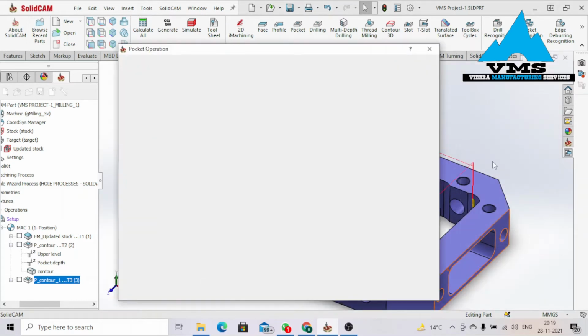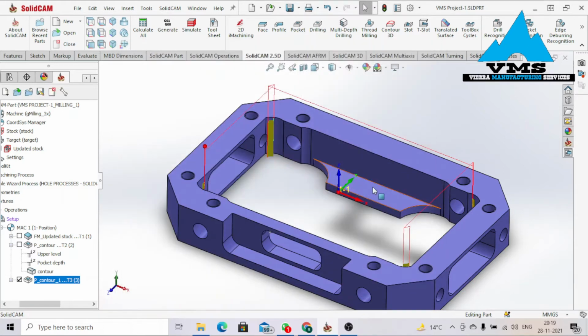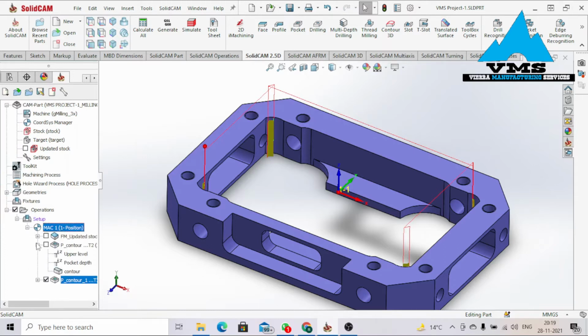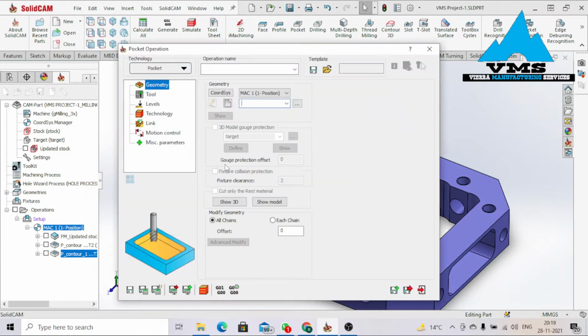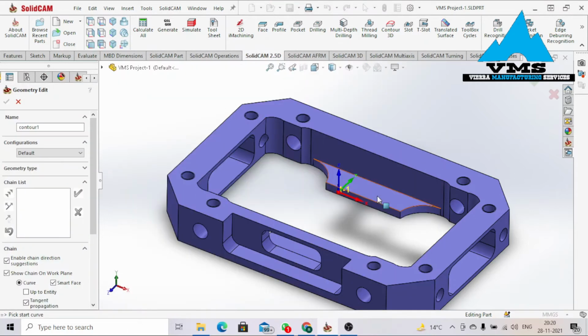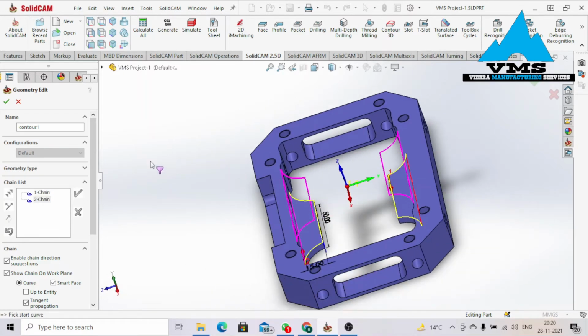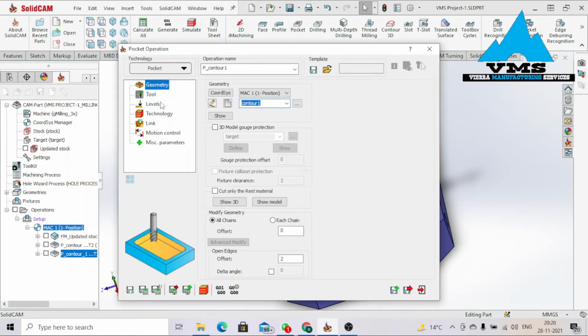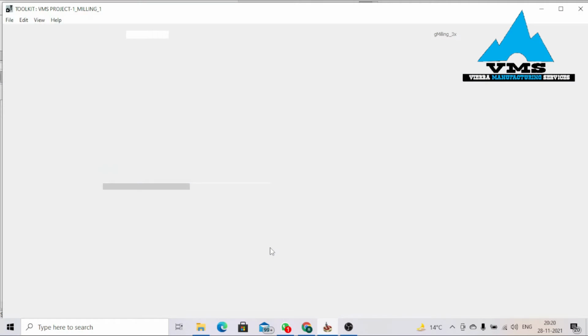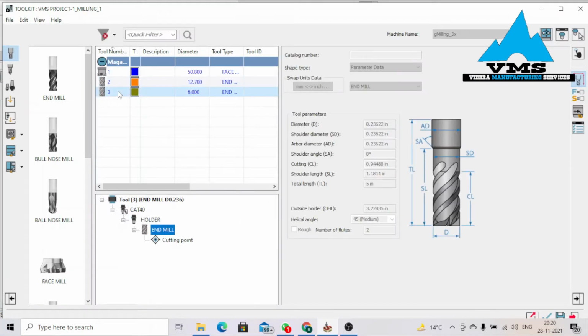So we have to machine this particular part. Let's look at this. Okay, close this. So for this part, it's equally a pocket operation. Let me just pull this down. Let me look at this. Okay, good. Looks nice this way. So I'll just untick this. Okay, pocket. You have to tell the software where the pocket is. So here it's the pocket. Good. And equally the other side. Fine. Tick. Okay. Tool, I'm going to use the smaller tool, 0.2.